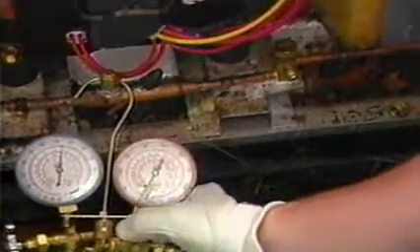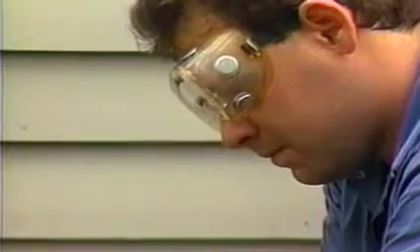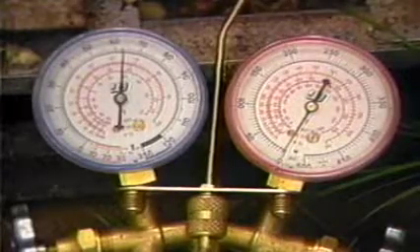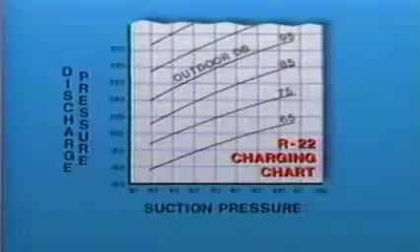These calculations are used to check the refrigerant charge in an air conditioning system. The approximate head pressure can be found in this manner. The suction pressure can be estimated. These methods should only be used, however, when the manufacturer's data is not available. Some manufacturers will have a charging chart attached to the unit or in a book for the unit. This chart will give you the pressures that correspond to the operating temperatures.